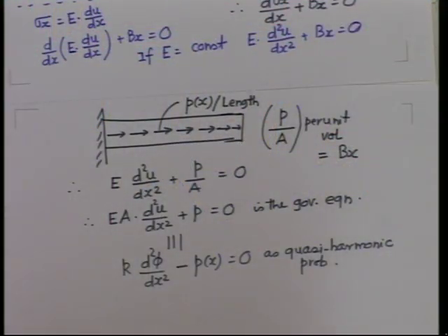That will be dealt with separately. Axial load, concentrated load, that will go directly to the node. You see, in FEM any distributed force is converted into nodal forces, because nodes are my key points. If there is a nodal force, that will directly go to the node. And Bx will be 0. Bx does not come there. Bx is always for distributed.